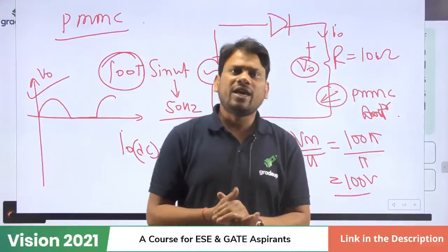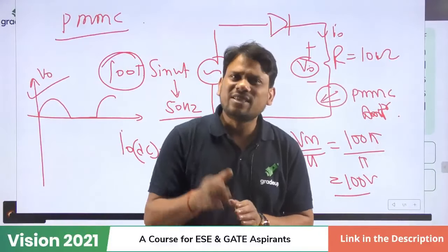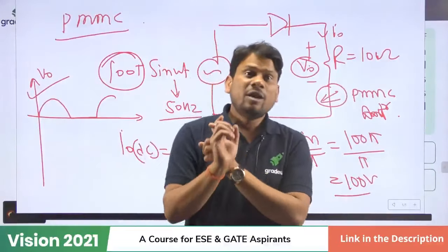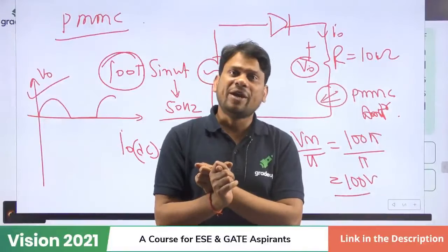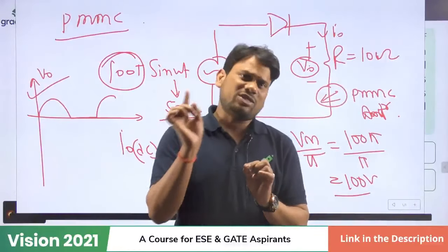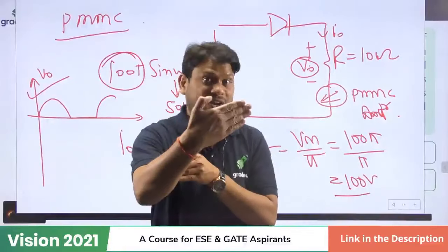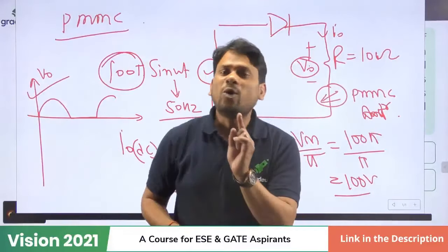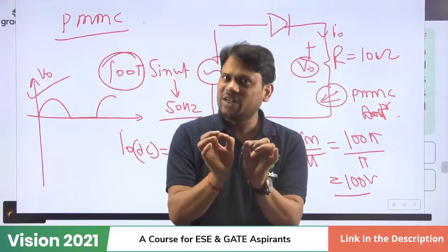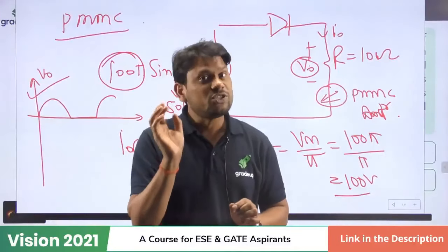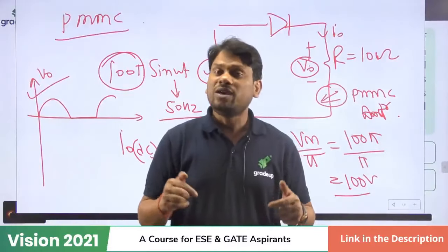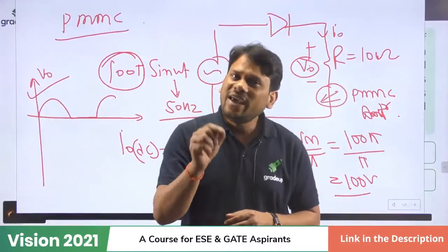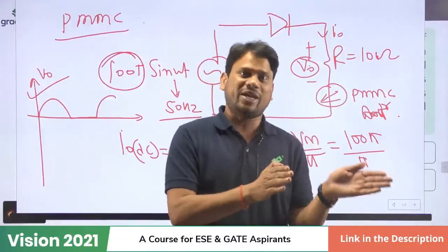So Sai Kumar, if AC with low frequency is applied, then the pointer will slowly move. Is that right, sir? Yes, definitely. Please try to understand, I am going to repeat. If we apply AC across the PMMC, our pointer will deflect. But the final result, that means in steady state, the pointer will not deflect and it will show 0. That's why we say PMMC definitely reads AC quantities but not average wise.